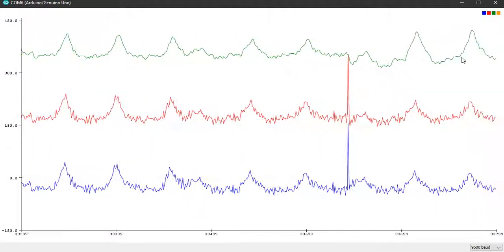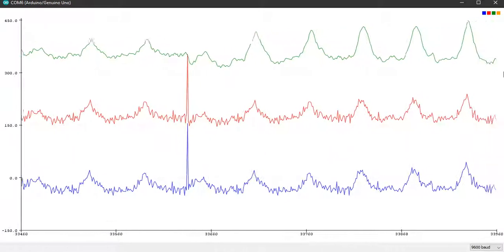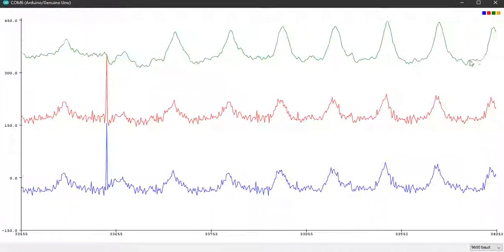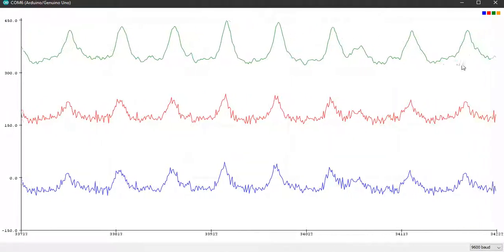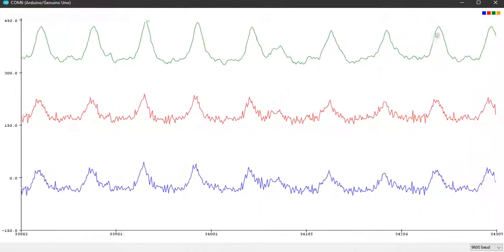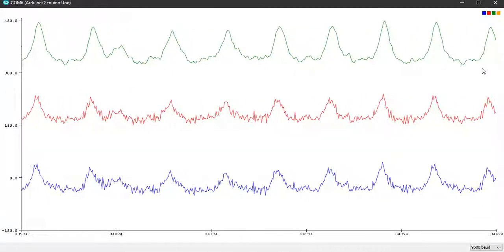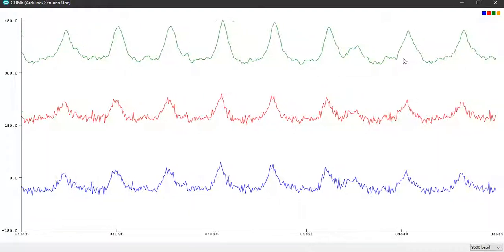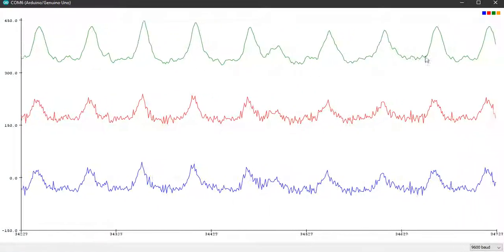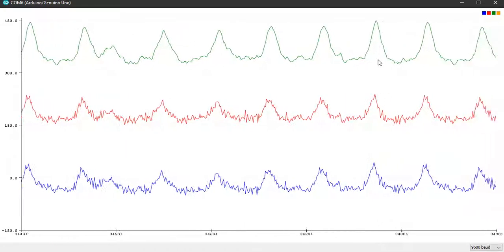As you can see, it's further smoothened, and you can see the peaks have got slightly amplified. So this is the effect of low pass filter. It relatively suppresses your high frequency components so that we are able to observe cleaner waveforms. Still more smoothing can be done, but it will be at the cost of loss of PPG data. As you can already see, the diastolic peaks, which are the minor peaks in the data, have really got suppressed by a large value.